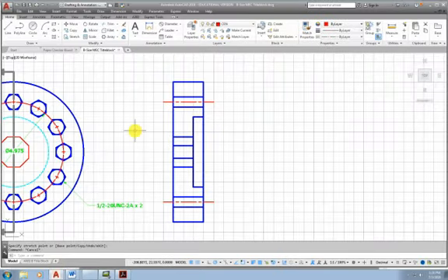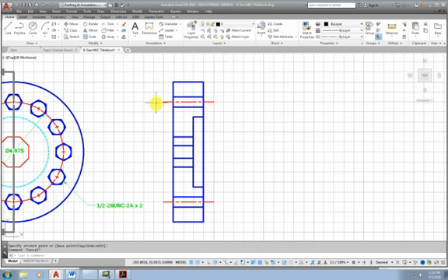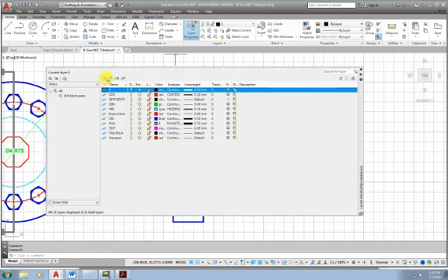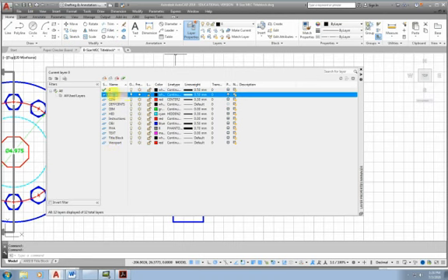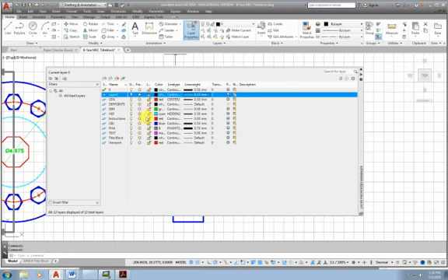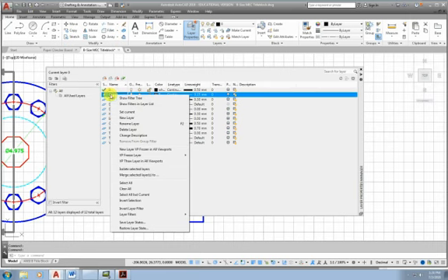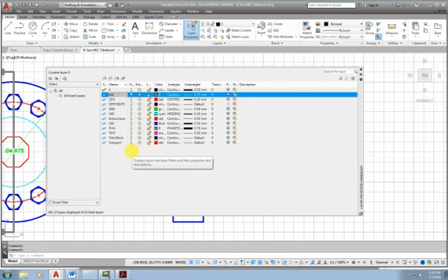I do have that line. So we're going to go to the hatch layer, and I thought I had a hatch layer, but apparently I do not. So I'm going to create one. I'll start on the layer 0, I'll say layer properties, and I'll say new layer, and it'll copy everything from that. And so I'm going to tweak down the line weight to 0.15 millimeters, and then I'll leave it as continuous, and the color will be gray. And then I'll rename that hatch.